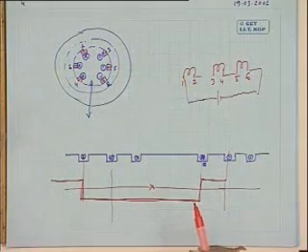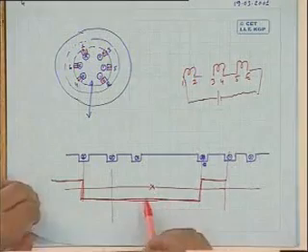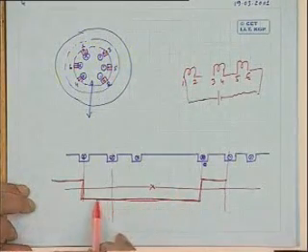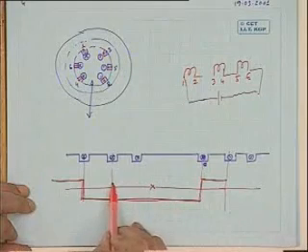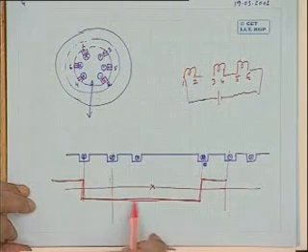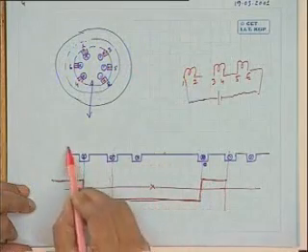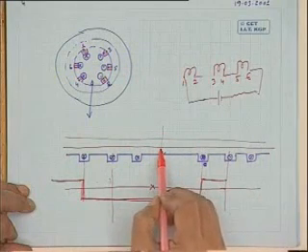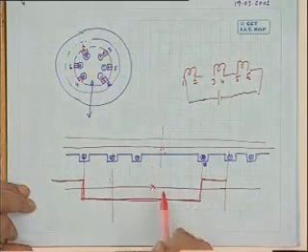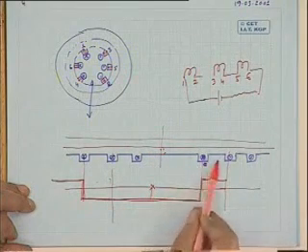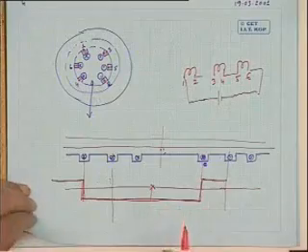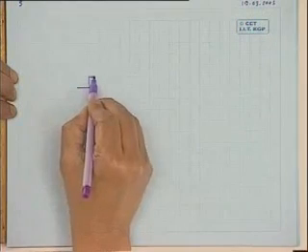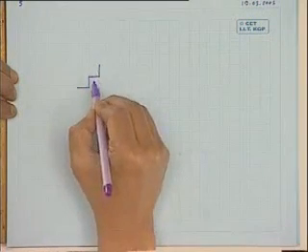So what kind of MMF waveform you will get now? You will get a stepped waveform. That is, this you can do. Is that clear what I am trying to tell? This MMF you find out. For this one also you find out its resultant MMF. For example, here at this position, suppose this is the stator. What will be the field? 3 Ni by 2. Because this plus second one plus third one. So the MMF distribution of such a system of 3 coils will be stepped in nature.